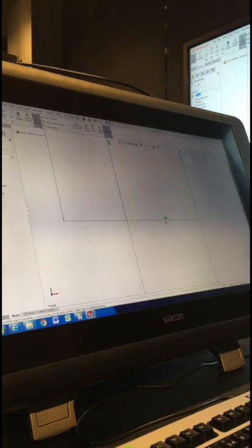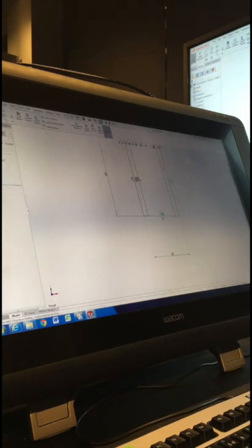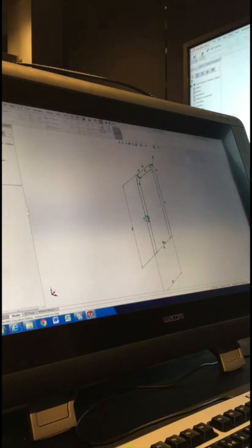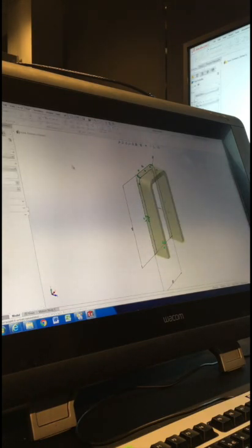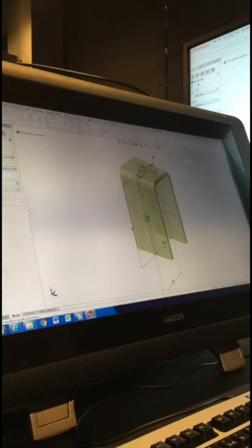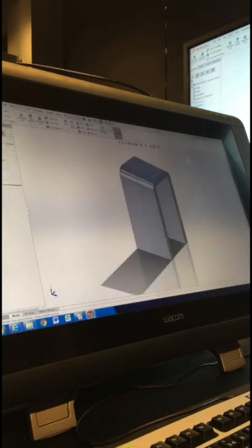Yeah, so that caps that bottom edge. All right, so that creates the entire shape for me. All right, so now that's ready to extrude. So I go features extrude, 25 millimeters. Like the bush though, we want to go symmetrical. So I change where it says blind to mid plane. Press OK.